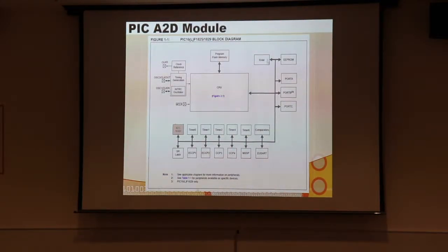We have random access memory out here on the data bus along with all the peripheral modules, and that's because we have memory mapped I/O on this chip. On your desktop or laptop, your computer memory sits completely elsewhere, has its own separate address and data bus, and has nothing to do with the I/O bus where all your peripherals sit. But in this chip, it's all the same because it's memory mapped, which is really as it should be.